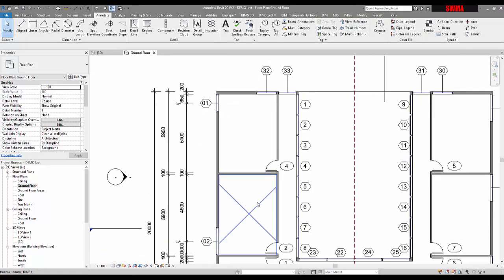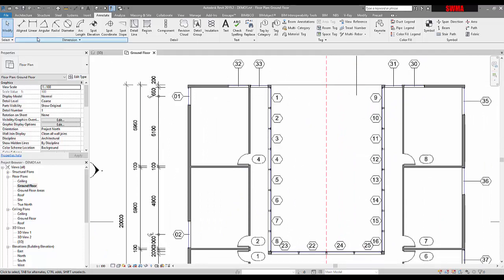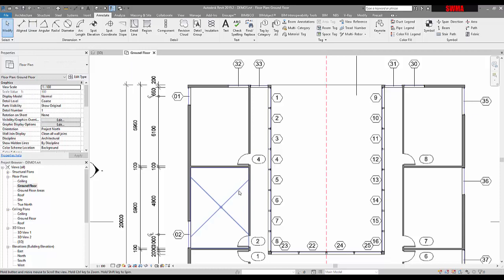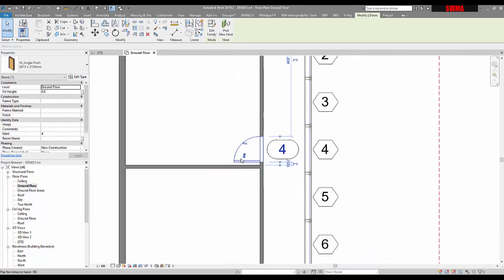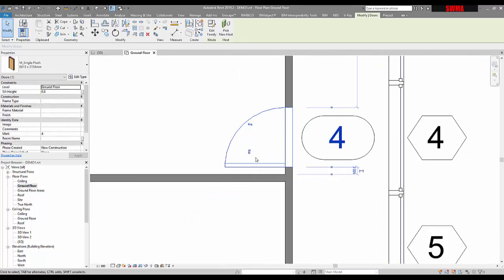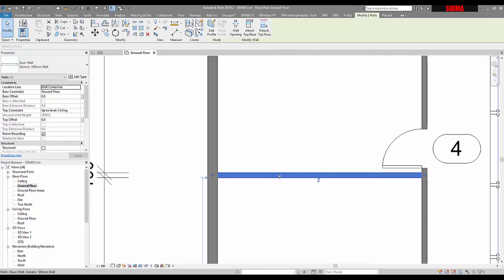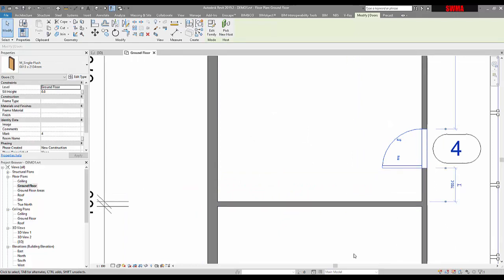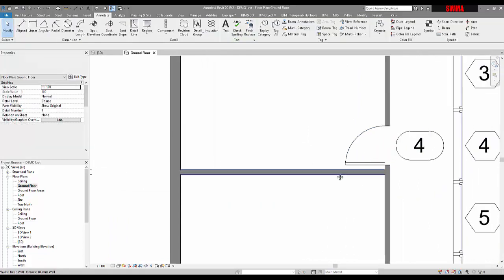Couple other things we could do here, just to show you about productivity with these tools. Maybe you want to have certain items aligned, so that when I go to move this wall, for example, I always want that door to be tracking against the wall. So you can create relationships with your dimensions.